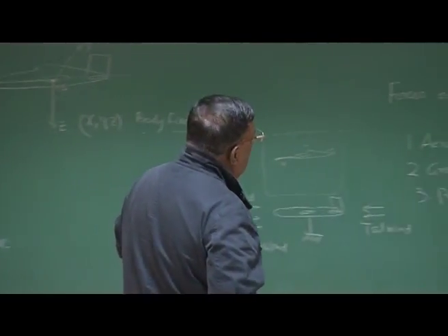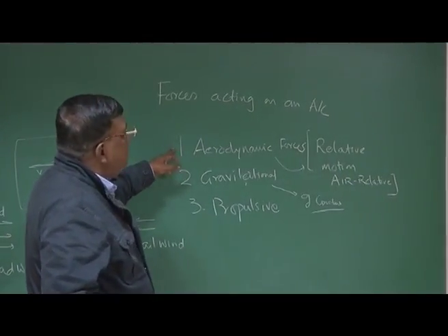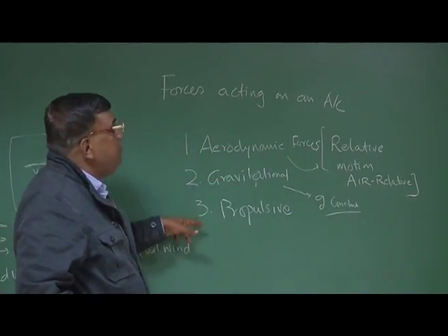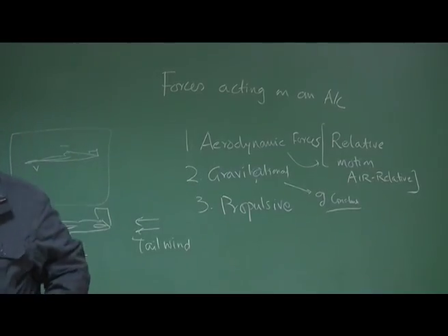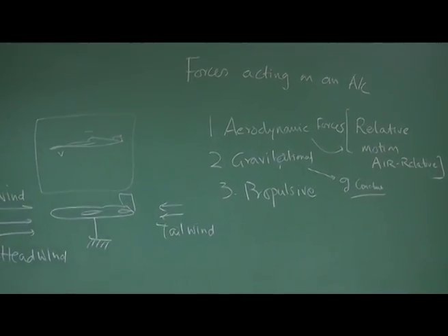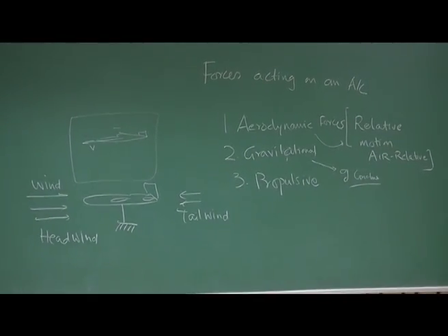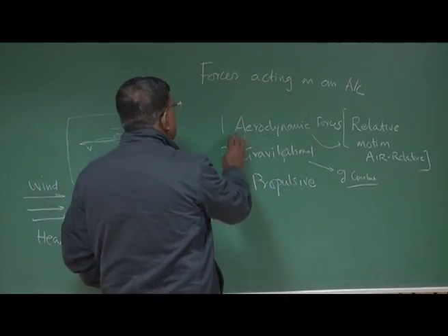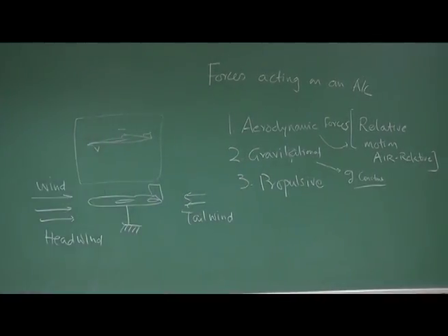However, you will have components in terms of moment about CG because of aerodynamic forces and propulsive forces, depending upon where it has been kept. In general we should be able to visualize this when we close our eyes and think. Once you identify the forces, the sources where force will be available for the airplane to interact, we now need to write the equation of motion.